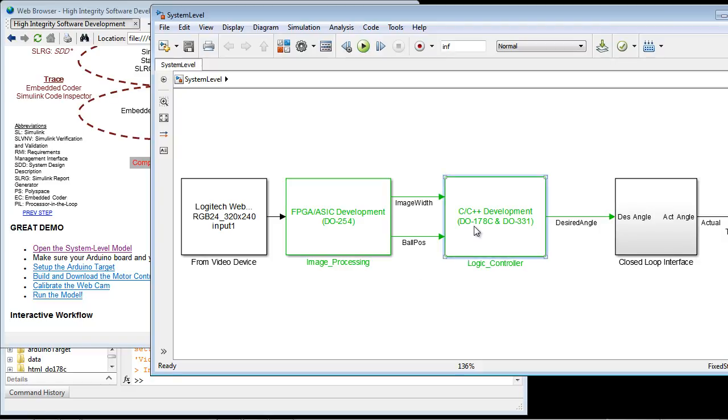And in fact, this is a large hybrid system, because for the component that we're going to focus on in this webinar series, we're planning on generating embedded software. The component of this system that is doing the image processing, we intend on implementing on an FPGA. So there's a whole other conversation to be had about how Simulink models can be used to generate VHDL and Verilog, and how this same or a very similar process that we're going to discuss in these webinars could be suitable for something like a DO254 type of project where we're developing complex electronics and hardware.